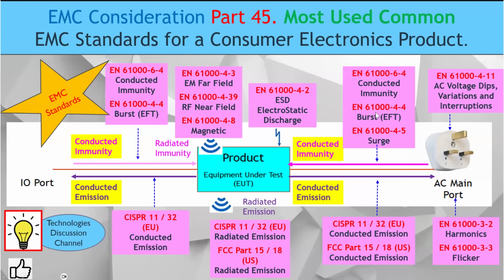Okay, so these two tests you are actually required to do for any cable that serves your product. But over here, you can see that this is a so-called AC mains. So you can see that I actually need to do some form of surge. And today, I actually want to emphasize this test, which is the AC voltage dip, variation and the interrupt test.